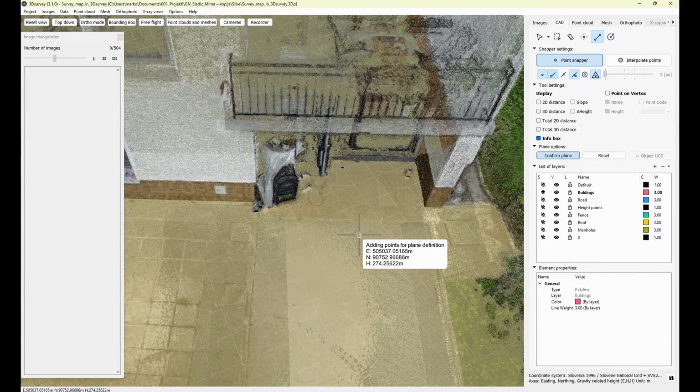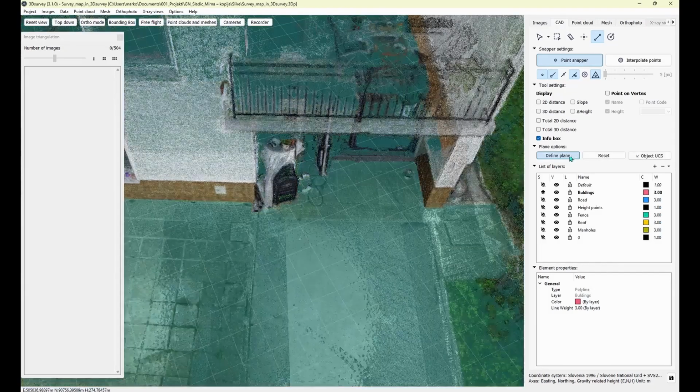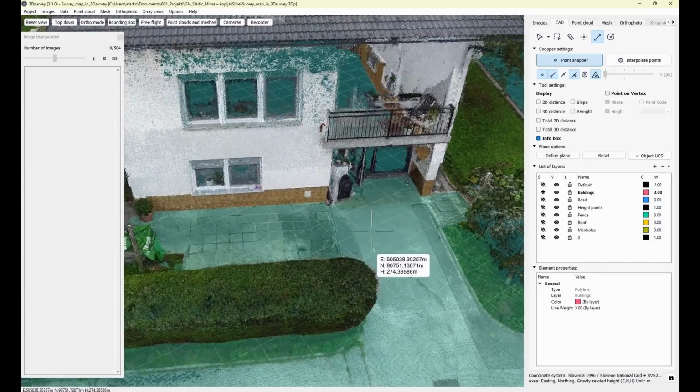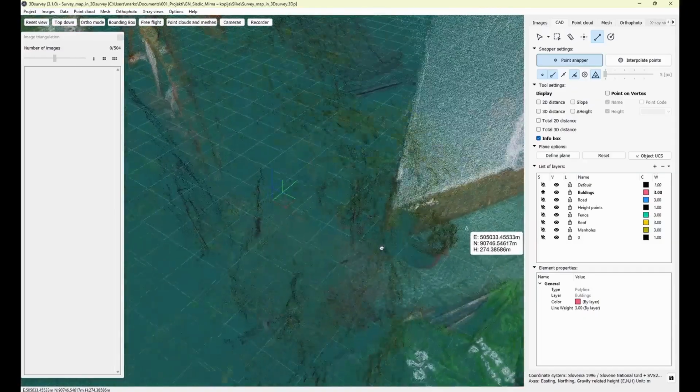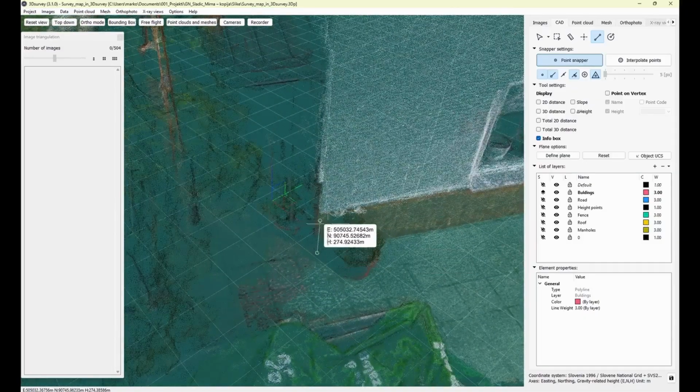But for the perfect horizontal plane, a single point, it's perfect: just click confirm point, and now everything I'm extracting on my point cloud will vertically snap to this plane I just defined. This is a very useful thing for extracting. And I need to decide it.